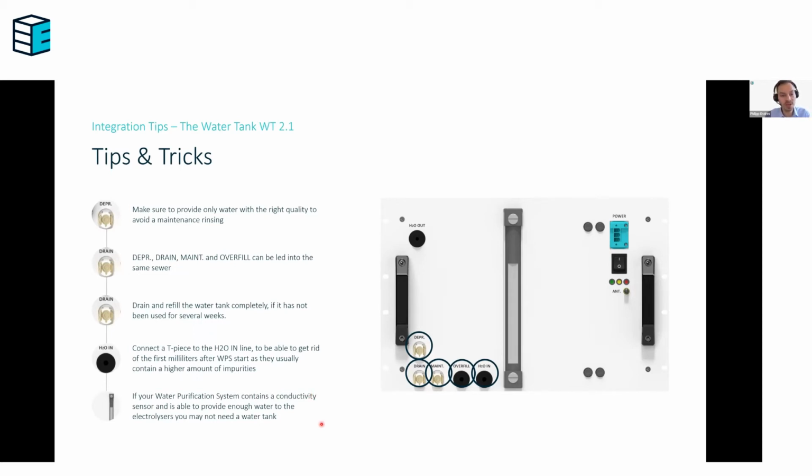If the WPS contains a conductivity sensor, then you're able to provide the water to the electrolyzers directly. You might not need a water tank. That depends on your individual setup and, of course, on the performance of your water purification system.